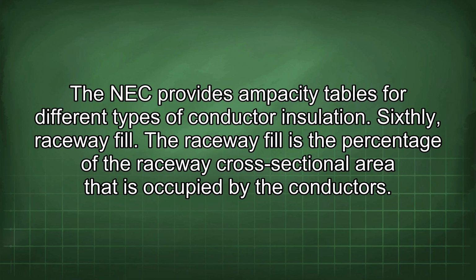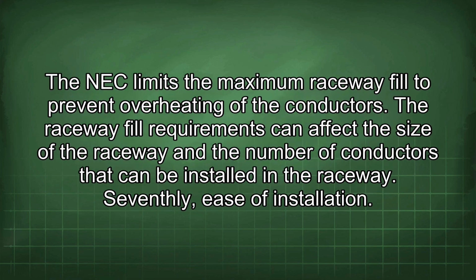Sixthly, raceway fill. The raceway fill is the percentage of the raceway cross-sectional area that is occupied by the conductors. The NEC limits the maximum raceway fill to prevent overheating of the conductors. The raceway fill requirements can affect the size of the raceway and the number of conductors that can be installed in the raceway. Seventhly, ease of installation.